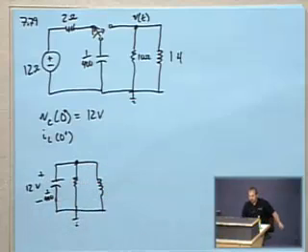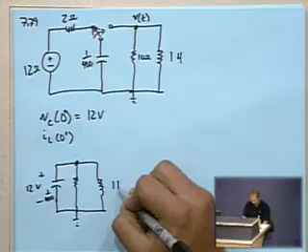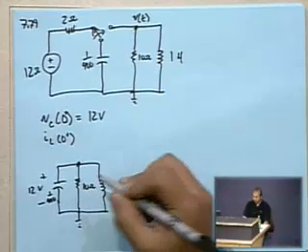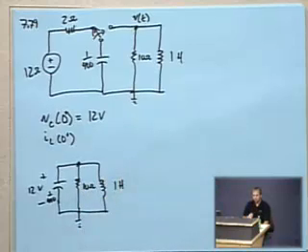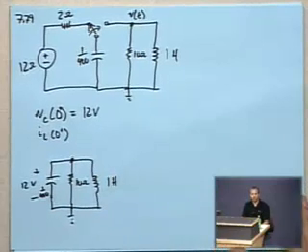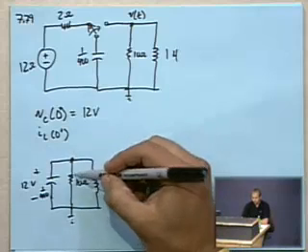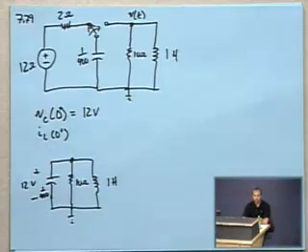And one of the other things that I did was I said, well, the current through the inductor, or the current through this capacitor can't change instantaneously, and so it's going to stay at 0. Well, that's not right. The current through an inductor can't change instantaneously. The current through a capacitor, that's fine. It can change like that. And you can definitely have the current in a resistor changing instantaneously.